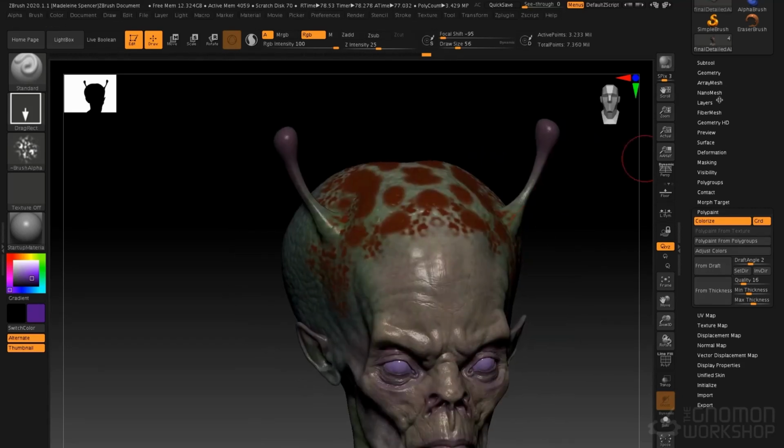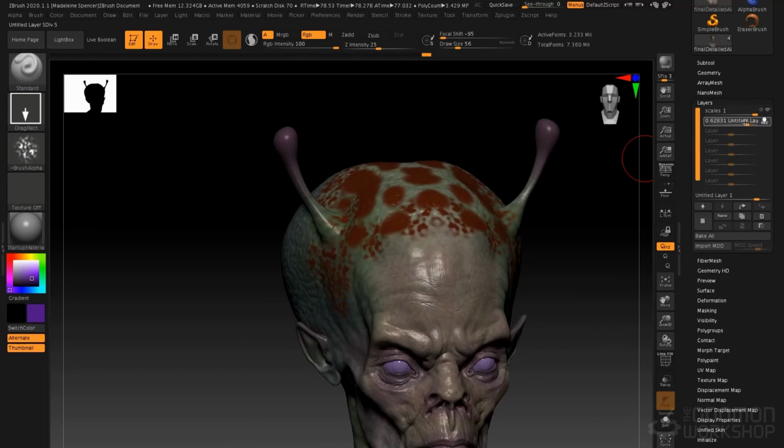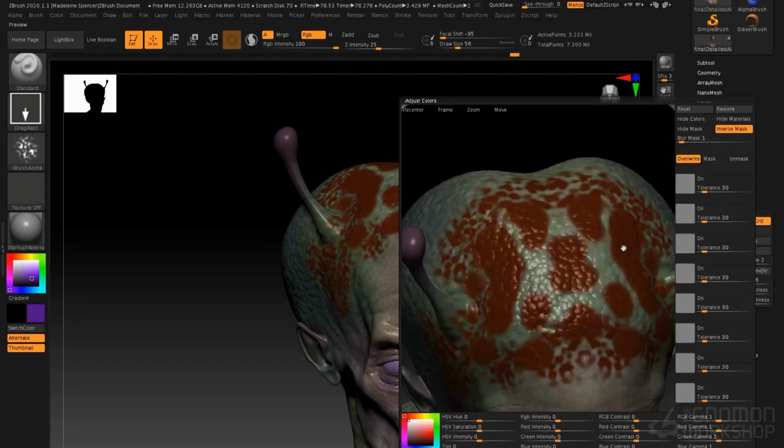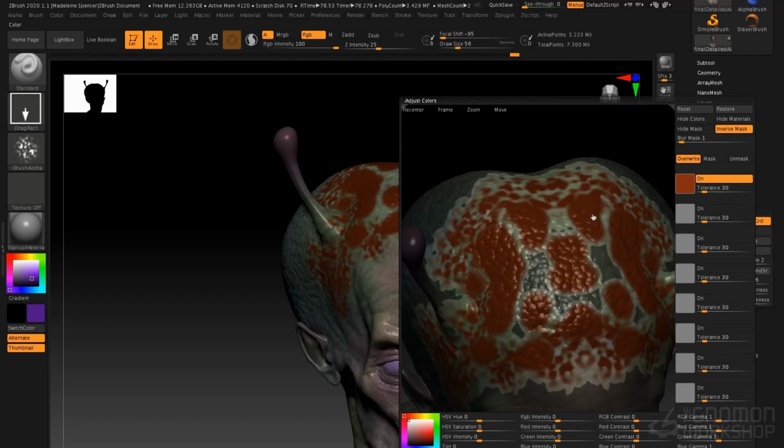inside of a layer. So let me go to my layers menu again, and if I adjust my layer opacity, I can turn that down into 0, removes it completely. I can turn it up a little bit, fade it out just slightly. I can duplicate this layer, thereby sort of changing the color intensity just by doubling it up. And then of course I can go in and do color adjustments on this. If I go into record, go to poly paint, adjust colors, and let's go ahead and do a color sample of that. Change our hue.